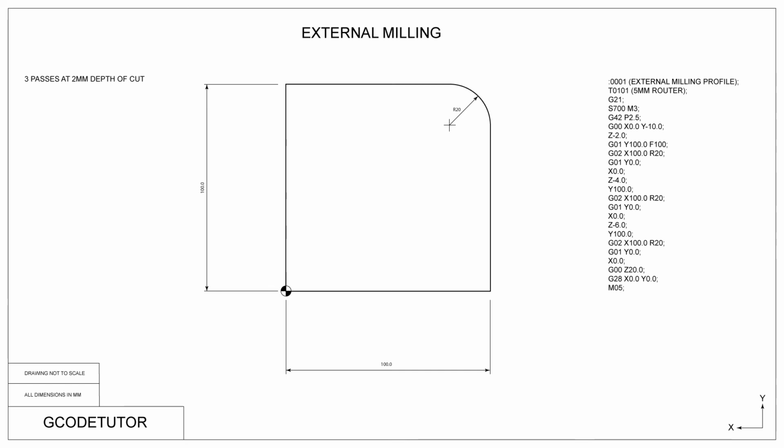The M05 command is a spindle stop command. And finally, we add an M00 command. This stops the machine, so we're ready to do a manual tool change or end of program.